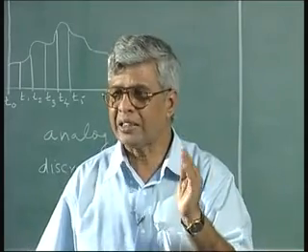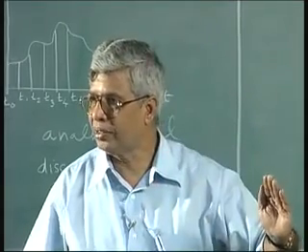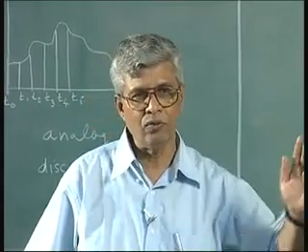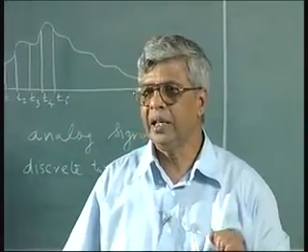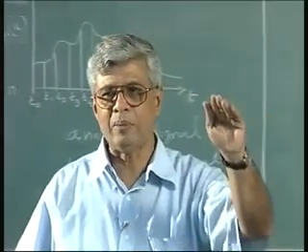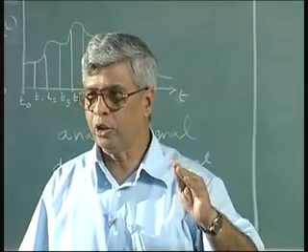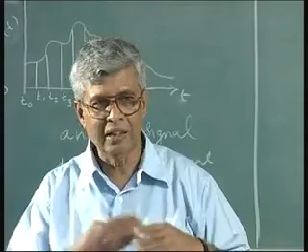So if I further discretize, I discretize the time to start with. Originally I had a signal with continuous time and continuous amplitude variation. Then I let the amplitude continuously vary but discretize the time. I am going to introduce one more discretization in the amplitude.